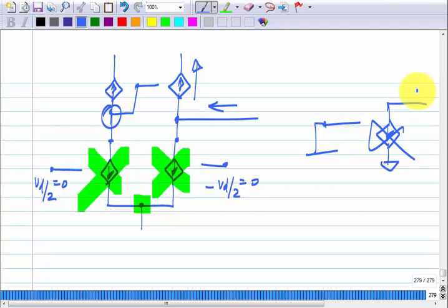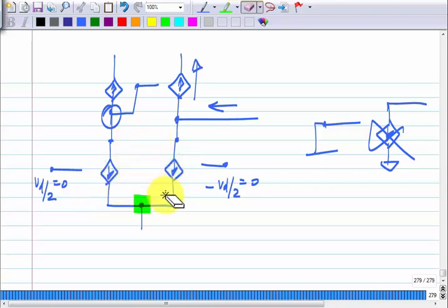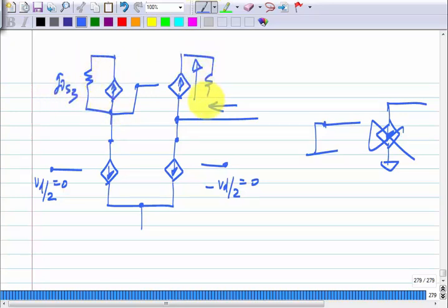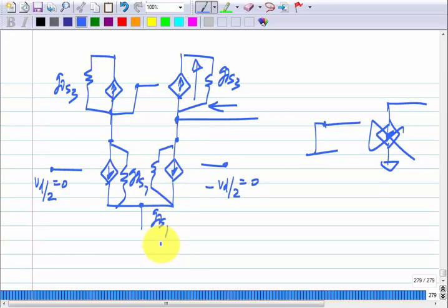So, now obviously, this is not going to happen in reality. What happens if transistors have output resistances? So, we will have something, GDS3. M3 and M4 are identical, so I will call this also GDS3, okay, and M1 and M2 are identical. I will call this GDS1. What will be the output resistance or output conductance?